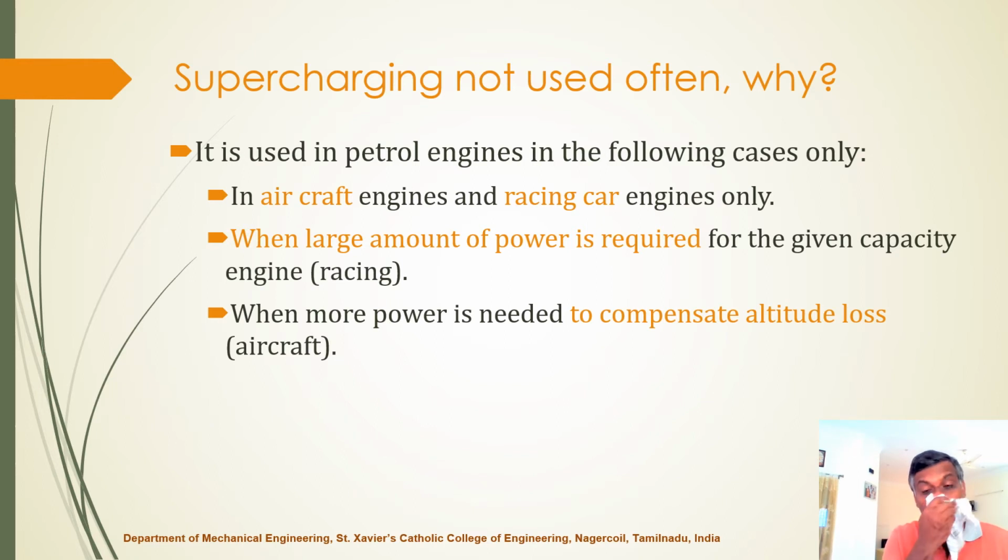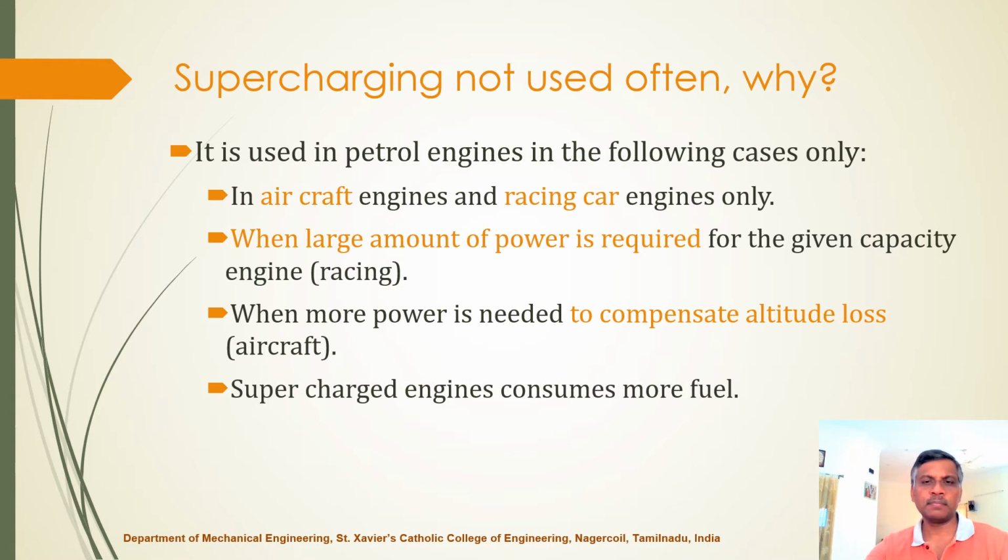Supercharging is used in aircraft. Basically, at higher altitudes, the pressure is low. The amount of air is low. So there we need supercharging, but not for ordinary vehicles because it consumes more fuel. Supercharged engine consumes more fuel. That is why it is not used in ordinary vehicles, our commercial vehicles. Because commercially we look for efficiency. With 1 liter of petrol, you should get more kilometers. That is how we look for it.